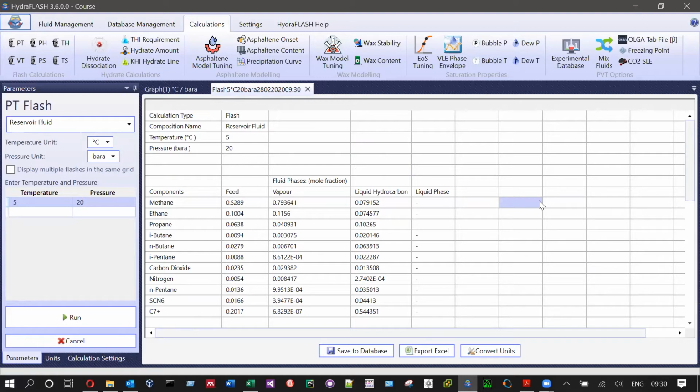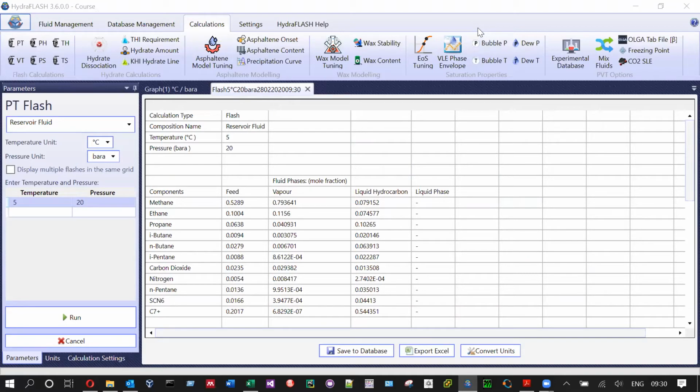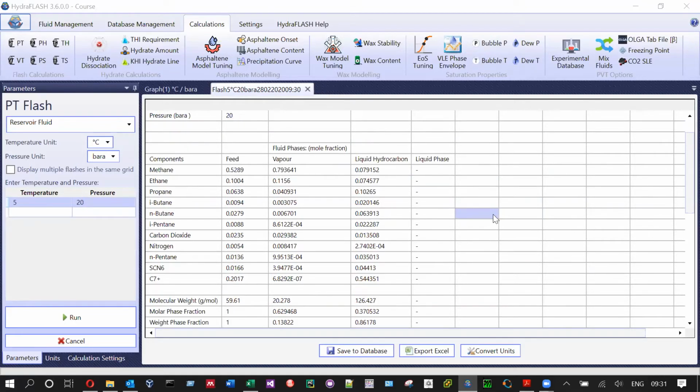That is depressurizing the pipeline to atmospheric on the surface, and then calculating the pressure at subsea condition, and then flashing the oil at that condition, then calculating the hydrate stability zone of the remaining fluid without methanol.